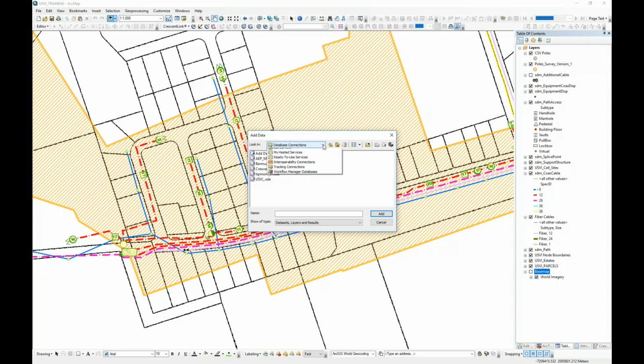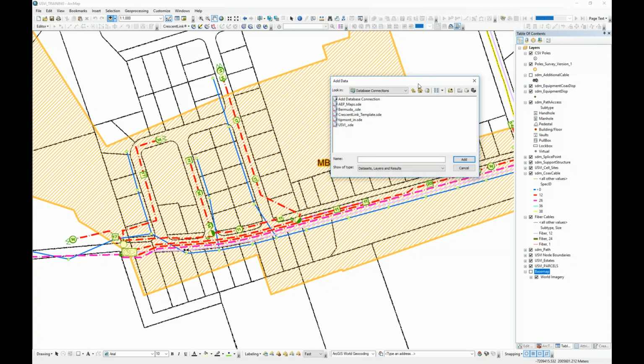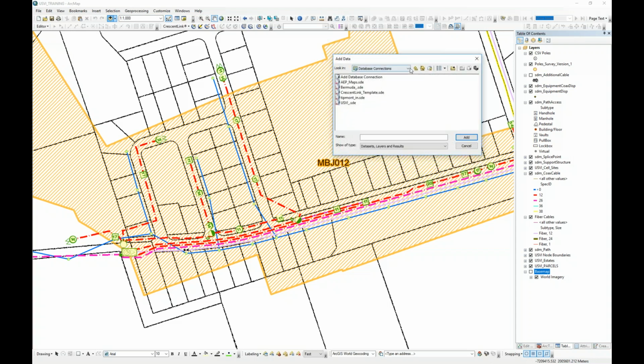True. So can I bring in images that we had created? You can, yes. You can bring in images you created. If you made them in CAD, you will have to bring them in, and you will have to physically put them on a point where you know they are correct spatially. Unless you've established a geolocate point in AutoCAD, and you know where that geolocate point is in ArcMap, then you can snap to that. That's a little more complicated. It takes some doing, but it can be done.